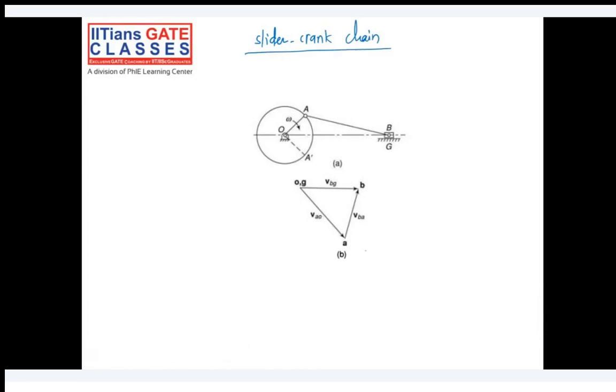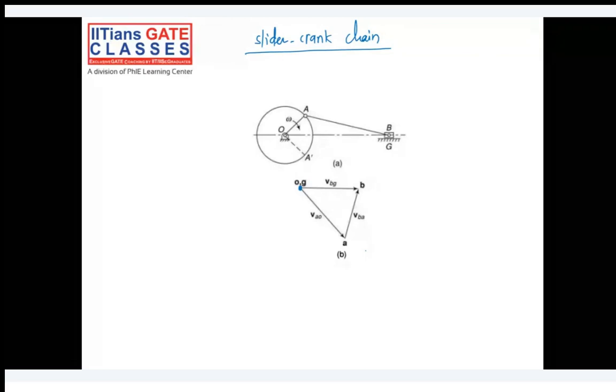Means the link 3 will have the same angular velocity, no, sir? We will take the ratio of velocities to the position vector. Basically here BCF is a constant link. So it's a shaded region, right? It means it's just a single link here. F is another point on that link BC, at a certain distance.